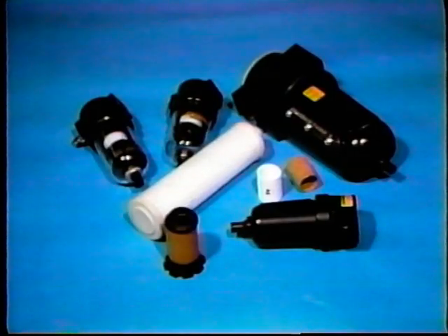So you'll find devices like these used in most pneumatic systems. They are all filters, and their purpose is to help remove contaminants from the air in our system. Remember back in Lesson 5, we said that the first line of defense for industrial compressed air is the compressor intake filter and the aftercooler. Well, the last phase of air preparation takes place at the individual pieces of equipment that are supplied by the air system.